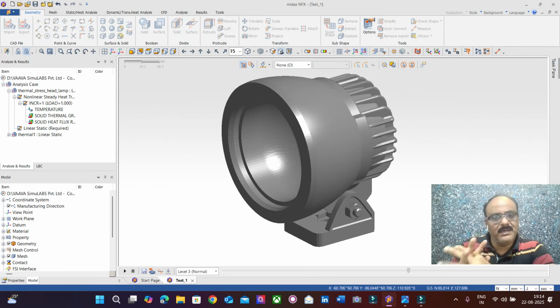So similarly here, like structural simulation, we can perform a thermodynamic simulation or a thermal simulation, but that will also have two types of simulations. So just as in structural we have a static simulation, here we call it a steady state simulation, and just as we have a transient simulation in structural analysis, which we refer to as structural dynamics, here also we are going to have a transient simulation. So apart from the static, the steady state, there will be a transient heat transfer.